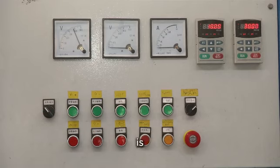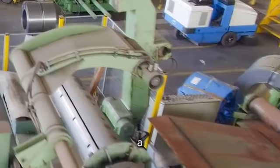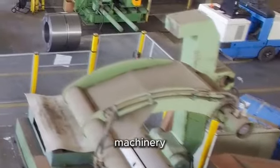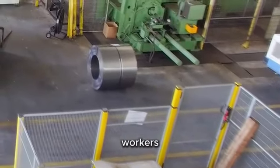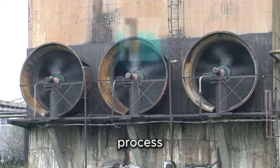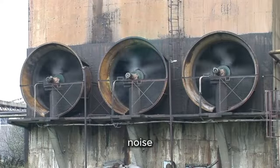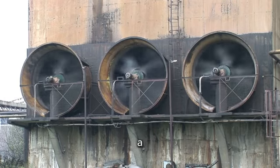The third level is engineering controls. These are physical changes to the workplace or the work process that isolate workers from the hazard. For example, if a job involves working with dangerous machinery, engineering controls may include installing machine guards to prevent workers from coming into contact with the hazardous moving parts. Or if a process generates loud noise, engineering controls may involve enclosing the noisy equipment or routing the exhaust gases through a duct to a safe area.